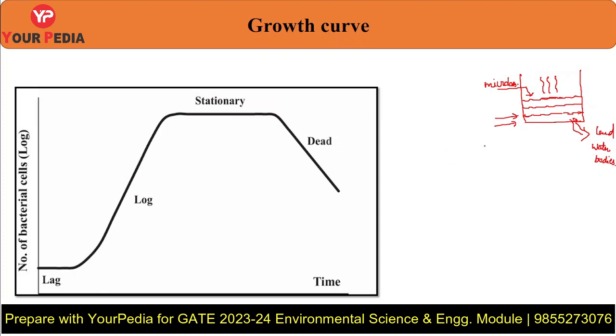Then the lifetime that is spent inside that sludge digester or bioreactor is defined as the growth curve, as shown in the left hand side of this. Okay, so what happens first? The microbes are introduced, the nutrients are added, and the microbes now enter the growth curve through lag phase. This phase is called the lag phase. The almost flat portion of this curve is lag phase.